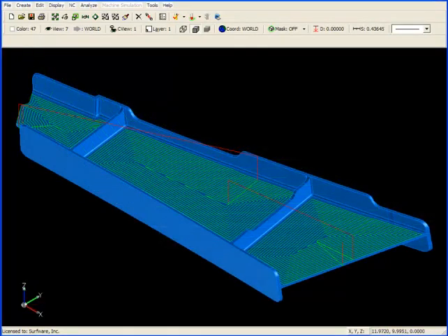In conclusion, flat surface machining can be a time saver when you're trying to machine 3-axis parts. It easily picks up the flat surfaces that are available to be machined and cuts them. Remember, however, that it does have limitations. Unlike 2-axis pocketing and 2-axis contouring, there are no peck levels available in flat surface machining. You will always machine at the ultimate depth of your surface.